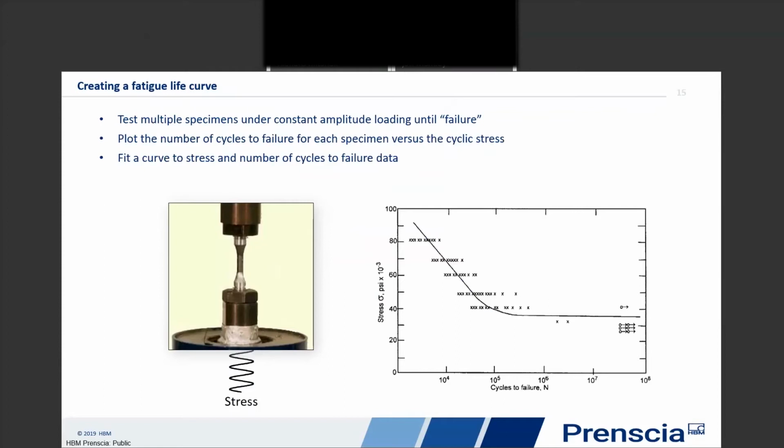So the way that we're dealing with the crack initiation portion of fatigue isn't substantially different than Wöhler was 150 years ago. The differences come in here that Wöhler tested an axle. His curve was his physical axle, so that curve had baked into it not only the fact that it was ductile iron, but it had the geometry, the stress risers ahead, the surface finish, any residual stresses.